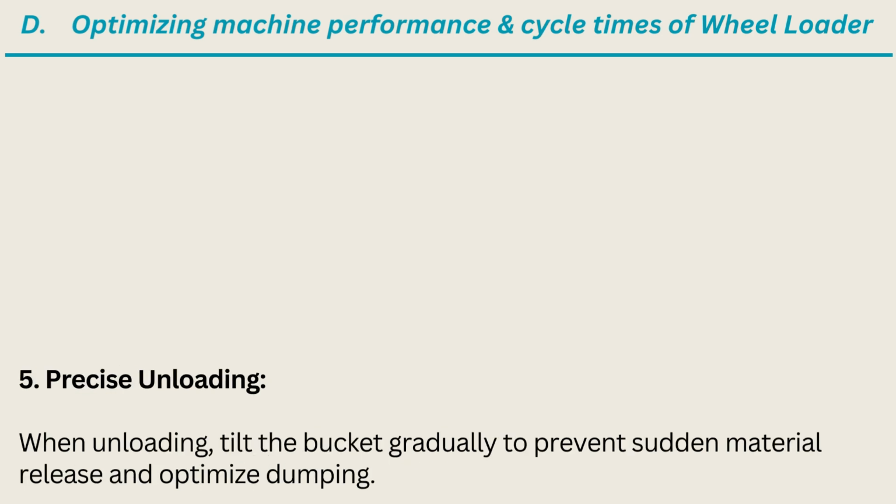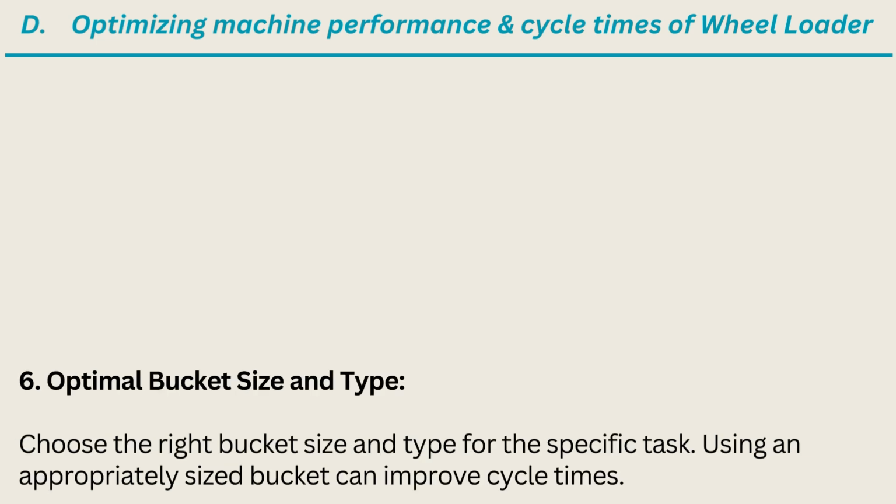5. Precise unloading. When unloading, tilt the bucket gradually to prevent sudden material release and optimize dumping. 6. Optimal bucket size and type. Choose the right bucket size and type for the specific task.